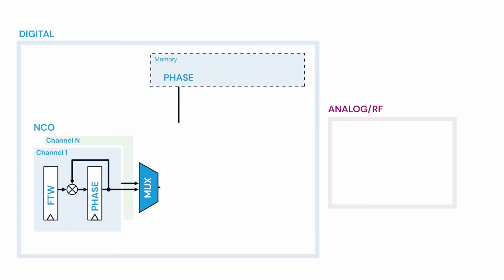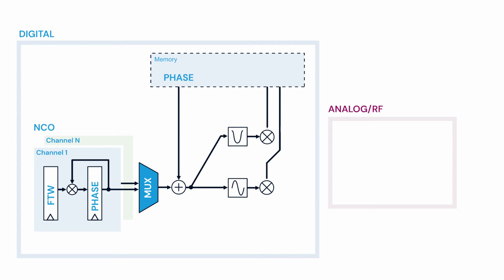And the first thing we can do is a phase modulation using data from a memory. This is an extension of what we have seen until now. Using two lookup tables, one for sine and one for cosine, we can generate the sine and cosine of that phase, and we multiply those signals by the amplitude that we want for these two channels, the in-phase and quadrature channel. Both the phase and the amplitude information are provided by memory that could be on chip. In this way, we have the maximum flexibility regarding the pulse shaping.